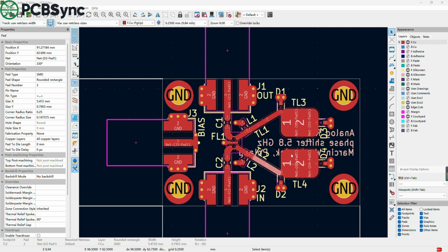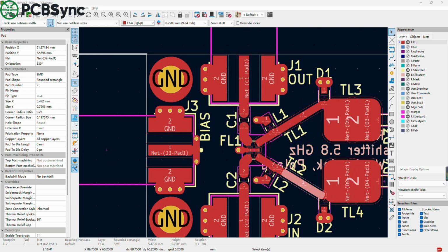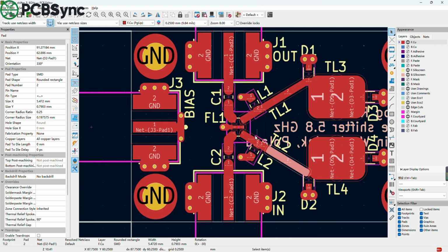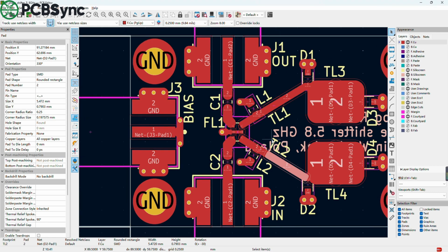In such high-frequency circuits, the PCB traces are no longer just simple connecting wires. Their length matters. The trace width, board thickness, and node length all jointly affect the impedance and electrical length. If the board's Dk value changes, even if the physical length of the copper trace remains the same, the signal passing through it may experience a change in the resulting phase as well. This open source project was originally designed for 0.6 mm thick FR4.